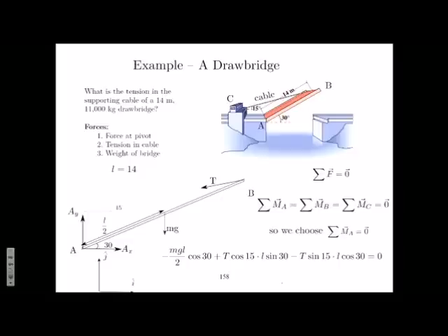How do we know that? Remember, you can always draw the circle that's tangent to the line of action. So this is the line of action, this is the point A. You make A your center and draw a circle such that the circle is tangent to this line of action. The force is pushing it downward, which means the circle, or the gear or the wheel, whatever you think of it as, is going to rotate clockwise. That means moment is negative, and that's why we have the minus sign here. Okay. So for mg, we use the perpendicular distance. Why?